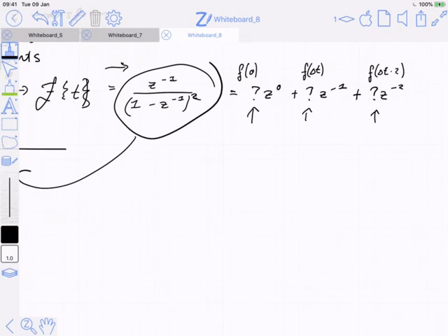We never want the infinite series, right, because we don't have time. So we always just use a couple of elements. We say, okay, we want to just plot the first 5 or the first 20. And if that's what I want, I can just do a fifth order Taylor series expansion, and I just get the result directly. Super easy. For my money, that's the easiest way of inverting the Z transform if you want to do it symbolically, right?